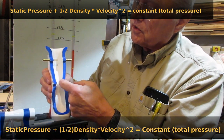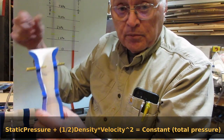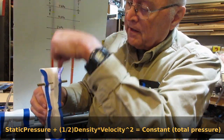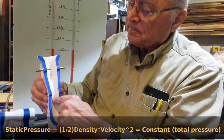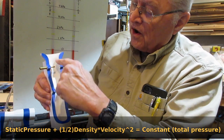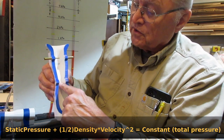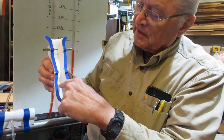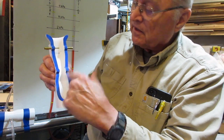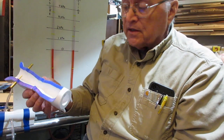The pressure you'd measure at the walls or with the static probe with the holes will change. But the dynamic pressure, the total pressure, measured by the pitot tube, should remain the same. And any loss in pressure is just due to friction and turbulence. And if you were to, when we go back, measure the total pressure in here, you see we get a lot of losses, okay? So that's how you could use it.